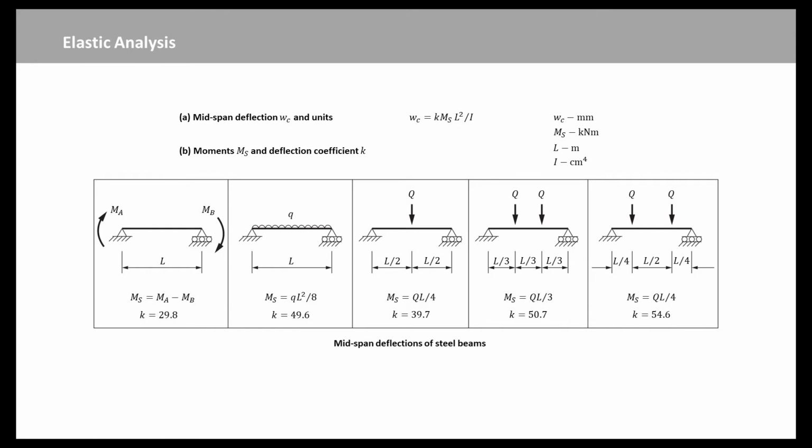Thus, in simply supported beams, it is usually accurate enough to use the mid-span deflection, like this figure. The mid-span deflection Wc measured relative to the level of the left-hand support depends on the distribution of the applied load, the end moments Ma and Mb taken as clockwise positive, and the sinking Wab of the right-hand support below the left-hand support, and can be expressed as this equation.